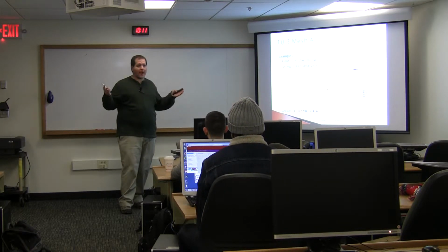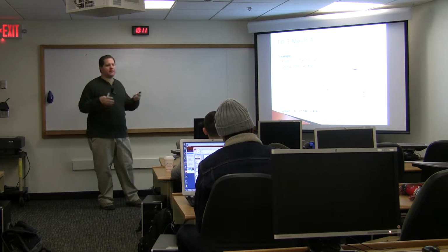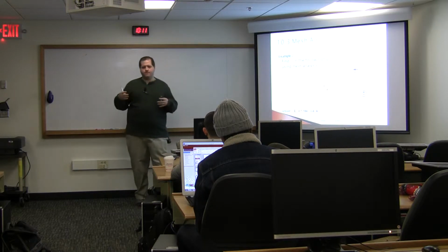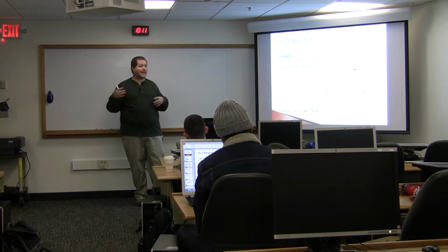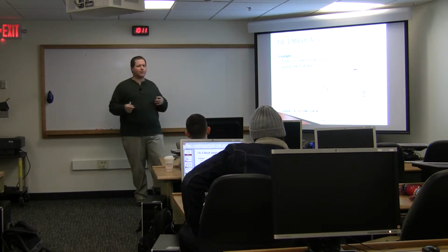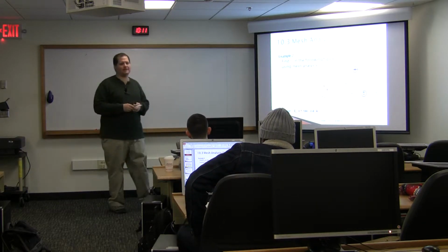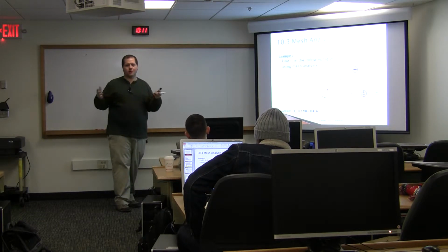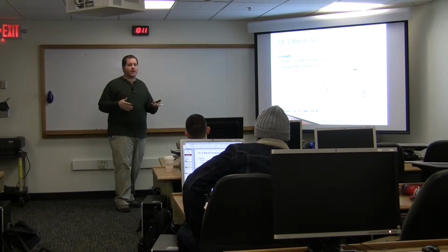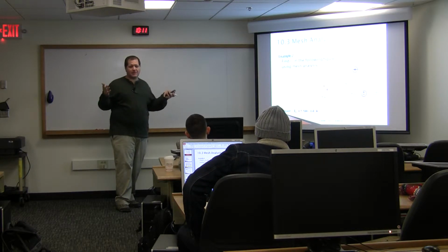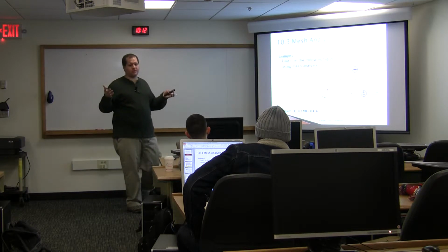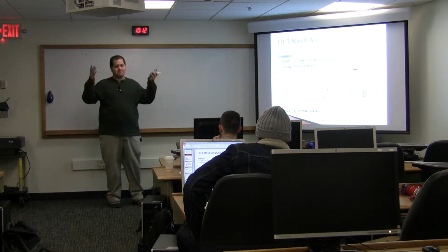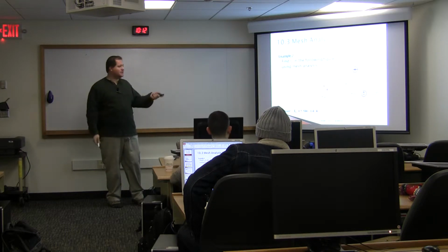So pick an omega, any omega that you want. Pick something reasonable. Multisim sometimes will outthink you if you try to go to really high frequencies, right? Or if you try to get really low, sometimes you'll see some little errors come in because it's not good at distinguishing between 0.0001 hertz and DC. But if you pick omega equals 1, the math is pretty easy. That's a little slow, but it'll probably work out just fine for Multisim at that point, right? So, and math is easy. If omega's 1, great, right? Omega's 1, that's easy. So you can put it in here.